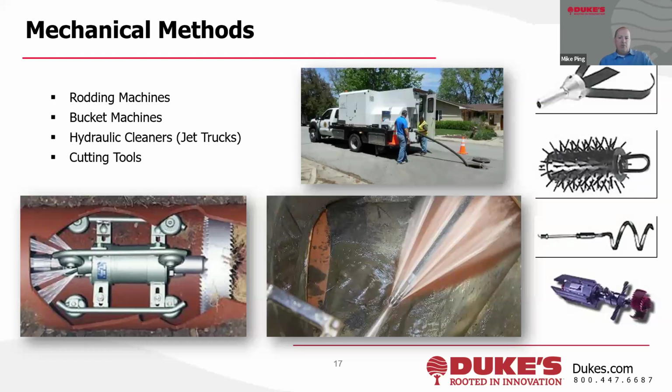So, rodding machines, personally, I don't see people using rodding machines anymore. That's where mechanical rods are connected, inserted into the sewer, and rotated. It's kind of like the sewer snake, the industrial version of the residential version that people have seen. Bucket machines, I hear of them being around somewhat, but that's a physical bucket that's installed in one manhole and mechanically pulled through, just ripping away whatever it is. The jetter trucks that jet at 80 gallons per minute is probably the most common value.